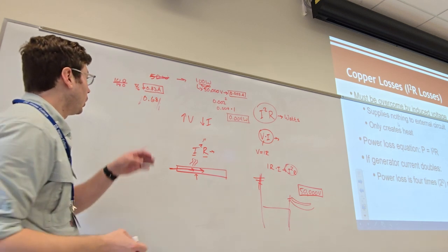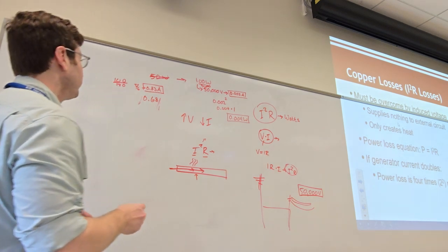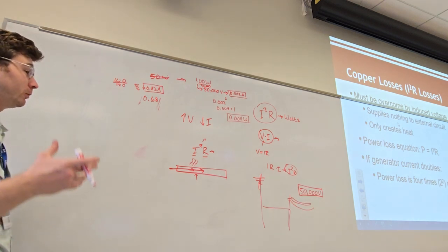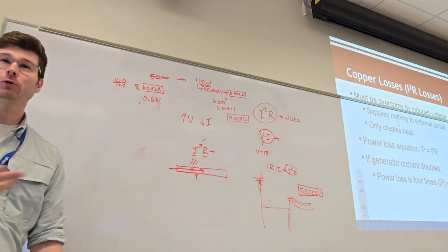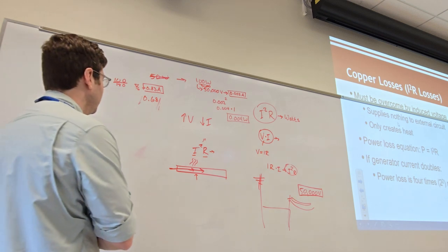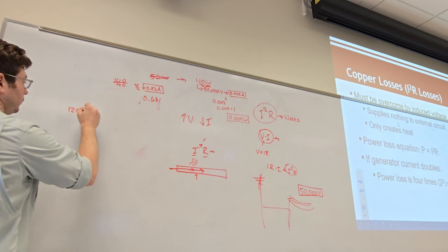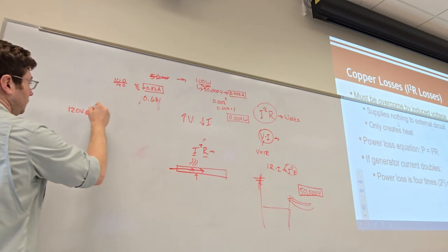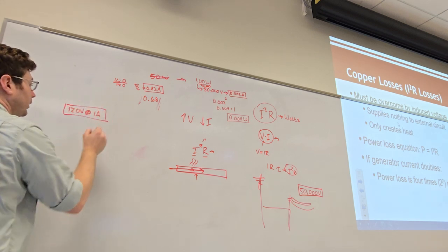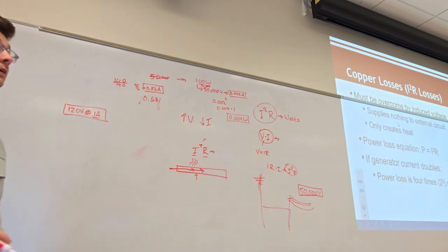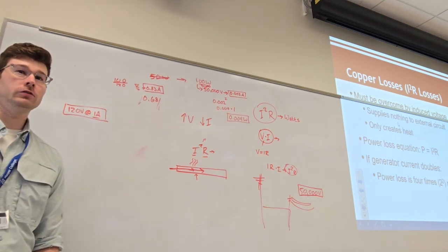Okay, at 120 volts. By the way, if we were sourcing a power supply that would only run that load, we could get away with a 120 volt, 1 amp supply. Or if we wanted to put a fuse on this, a 1 amp fuse would probably be a good idea, because anything over 1 amp is overload.